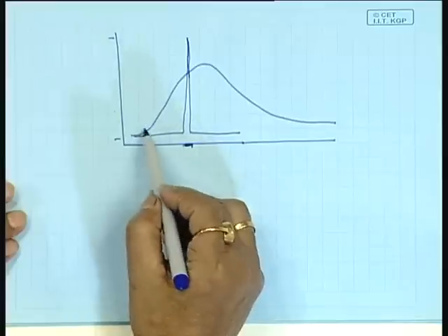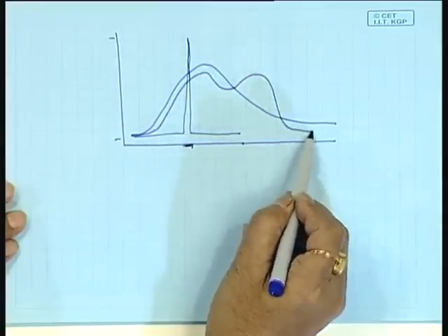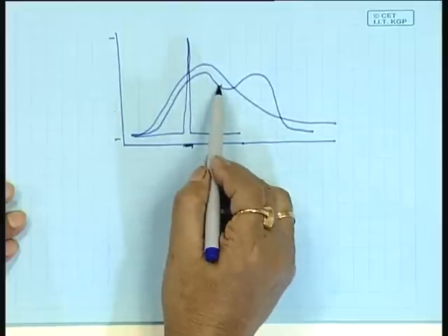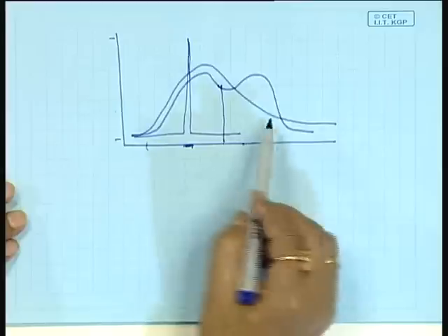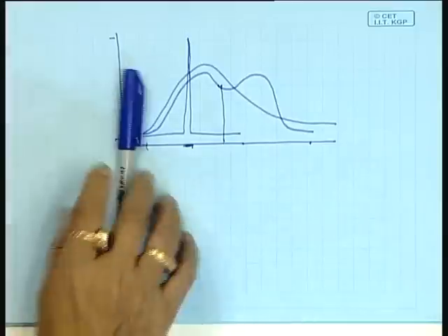Now, here you have seen one curve which looks like this distribution, it is a bimodal distribution. That means a certain fraction has this molecular weight and certain other fraction has this molecular weight. That means it is a mixture of equal amounts of low molecular weight with high molecular weight polymer. So, that has a profound effect on the processing and fabrication of the polymer. The melt viscosity, melt behavior, solution behavior, all those properties are controlled by this.